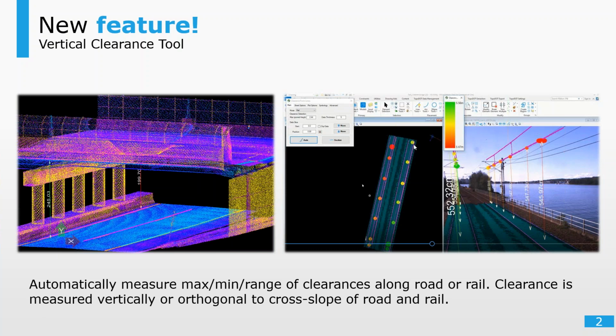In this case, it actually color codes. You can put a gradient, so you'll see every measurement. They're not evenly spaced because it will always be the lowest point. And then it also gives you the absolute lowest point, which is a big red dot, and the highest point, which is a big green one. So the bottom line is, from the top view you can see the trends as they're happening, and then of course you can see the individual measurements down here.